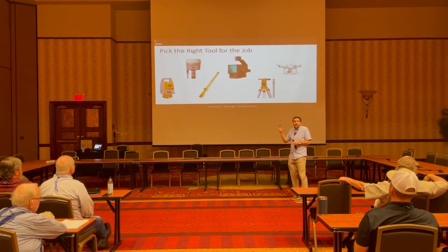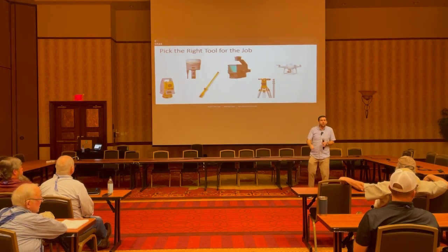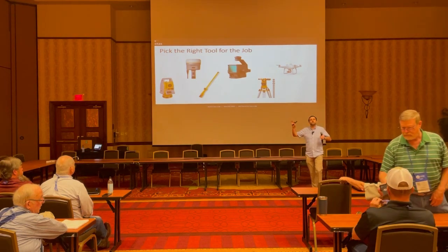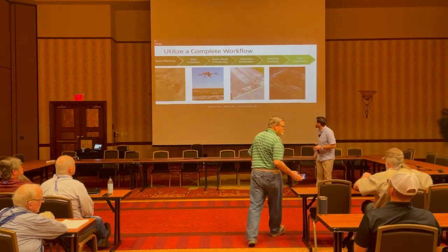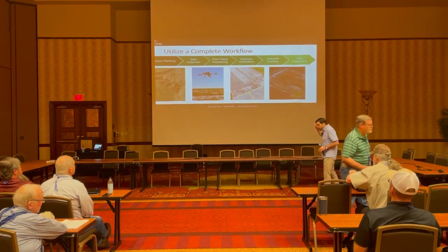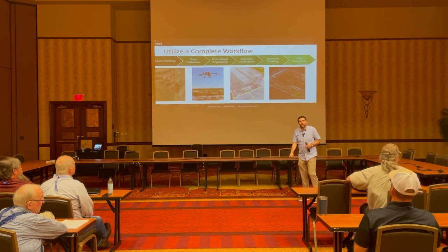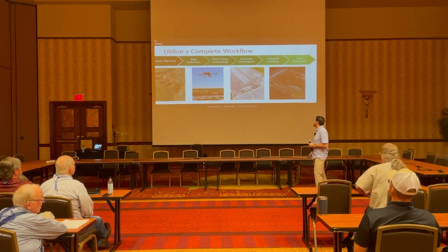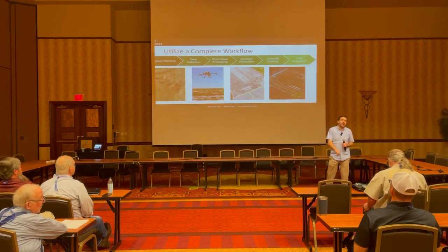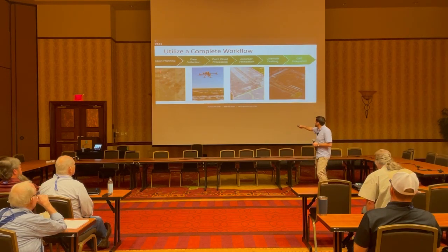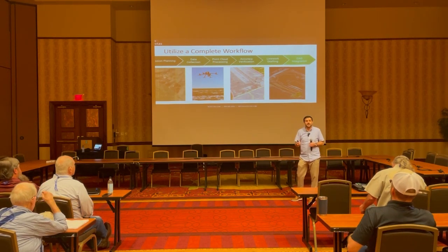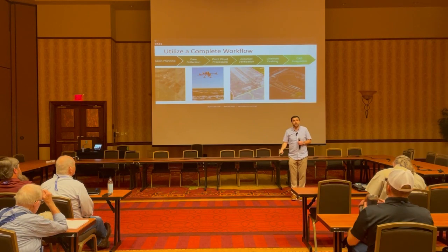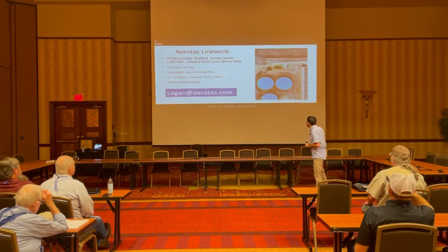And that means pick the right tool for the job. The drone is a wonderful tool. Drones can do so much in surveying, but they can't do everything, and they're not right for every single job. You also really should use a complete workflow. Take the 2 minutes for mission planning. Take the 2 minutes for accuracy verification. Those little steps right there, they're so small in the amount of time that they take, but so massive in the amount of time and headache that they can save you.